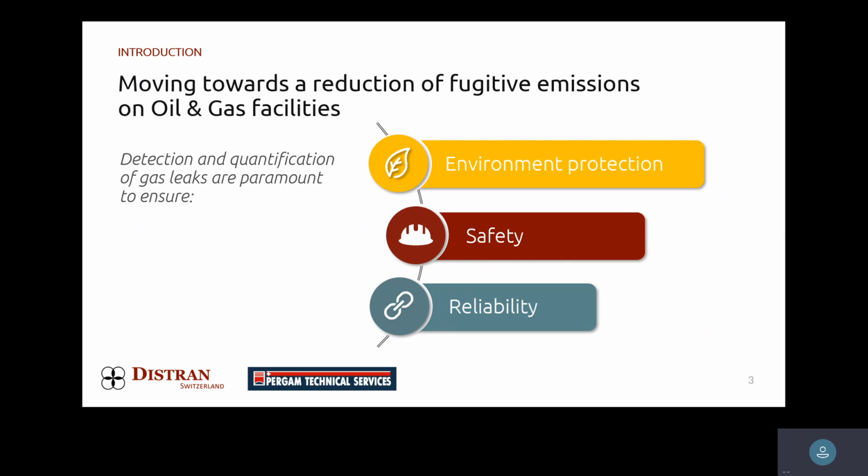The ability to go from ppm, from LEL and percent gas to a quantification situation has entirely changed the way the industry has accepted volumetric quantification in real time. This camera, within tens of seconds, has the ability to focus on the largest leak in the environment and quantify it for you. Why? Because it's not gas specific, it operates off pressure. And we're going to go through that here shortly.